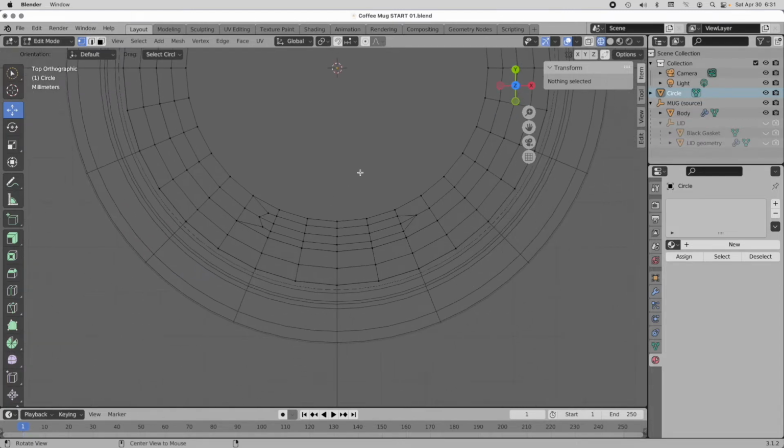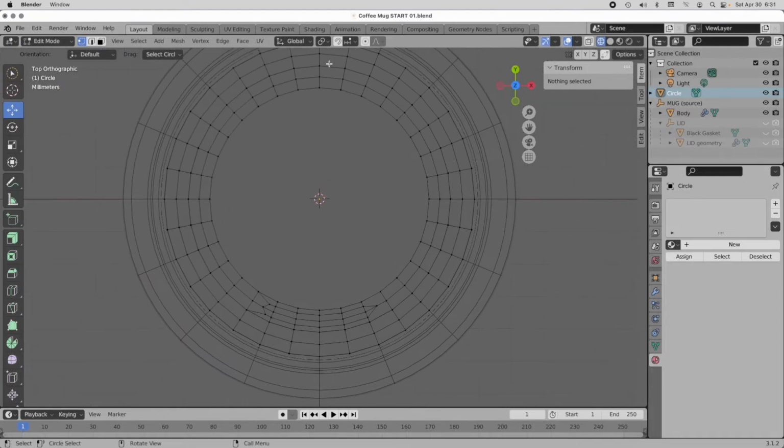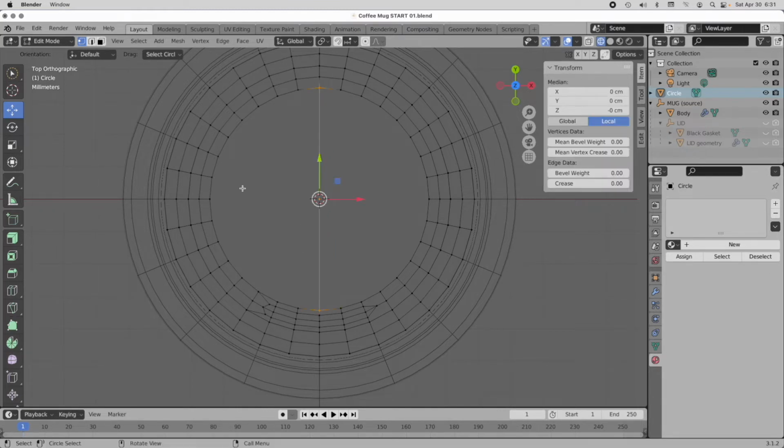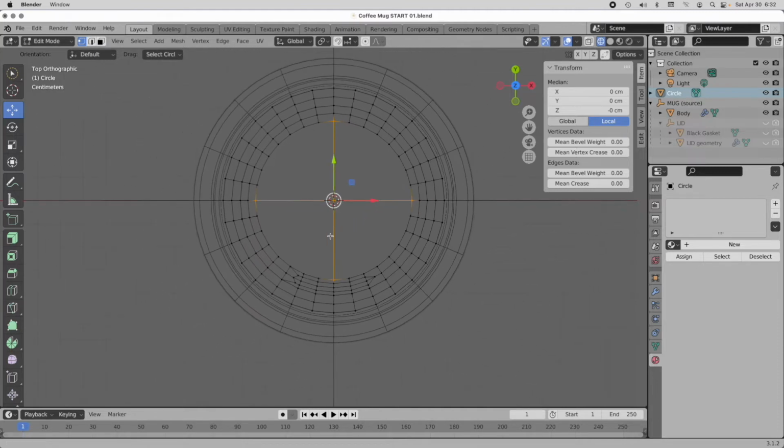Let's do this. Let's come in and add some geometry that we're going to need to make this symmetrical. I'm going to press the K key again, and I'm going to click here and come to here, hit return, K key again, click here, come all the way across here. It's going to cut across there, and click and hit return. Okay, so now we can cut in half and do symmetry operations as needed.